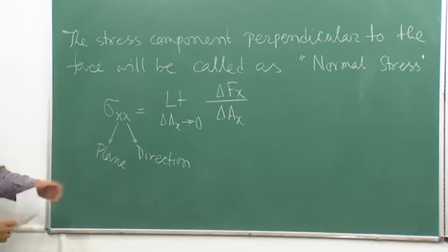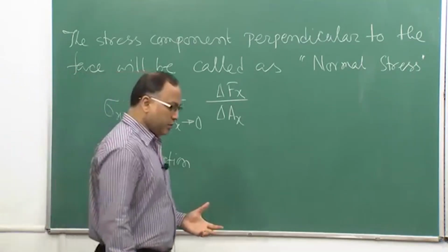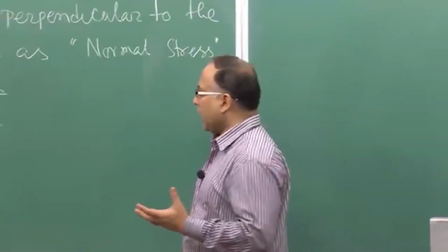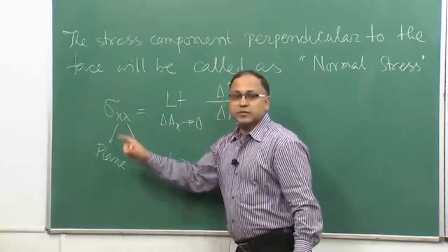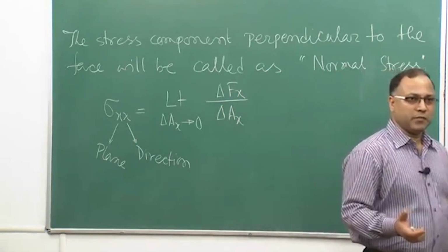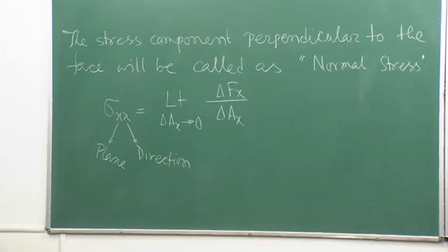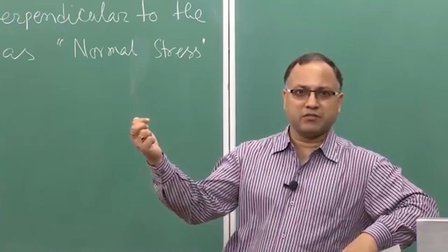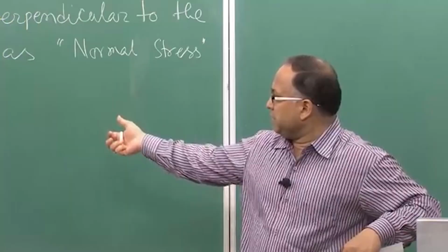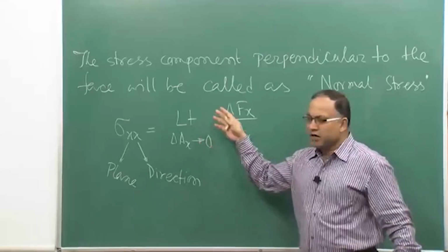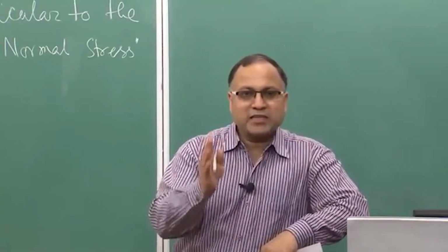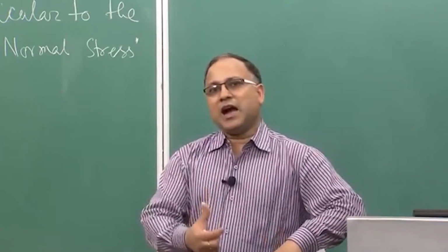When we are defining normal stress, both the subscripts are the same. Why? Because normal stress acts on that particular plane along the same direction. If this is the normal stress we are defining for the x plane, it acts on the x plane and along the x direction.